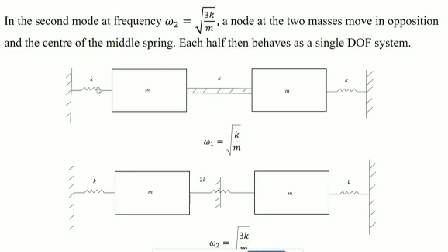That means, you see, the stiffness becomes, what is delta 1? Delta 1 will be, in that case, P is the same, so P by K1, and delta 2 will be P by K2. Therefore, delta 1 plus delta 2 will be P by K1 plus P by K2.